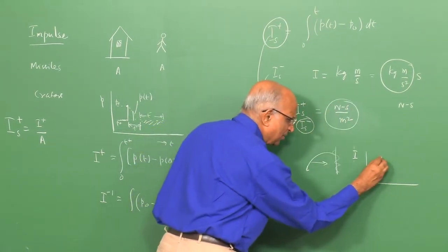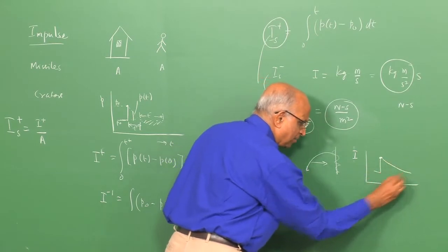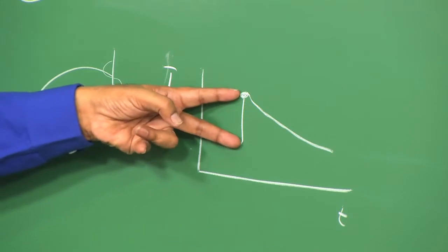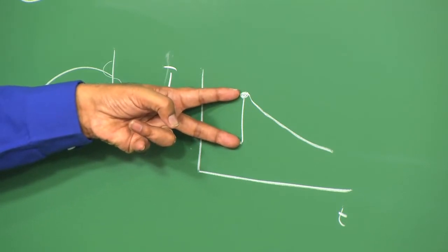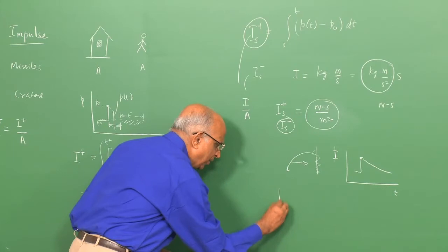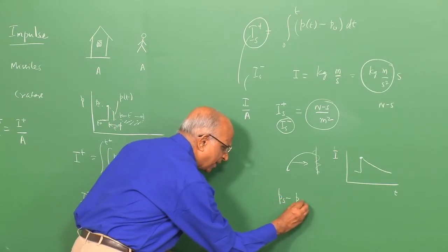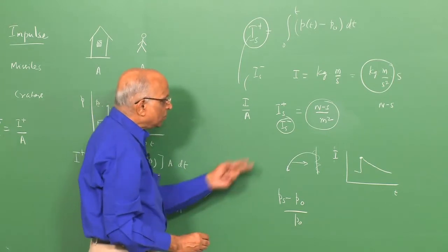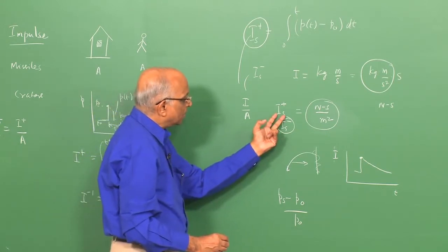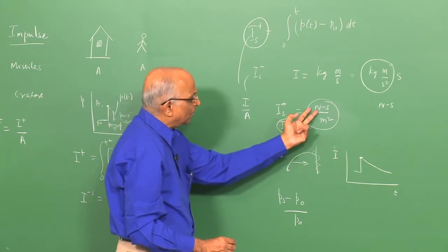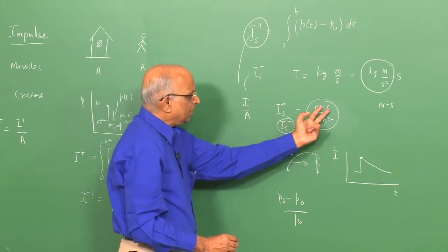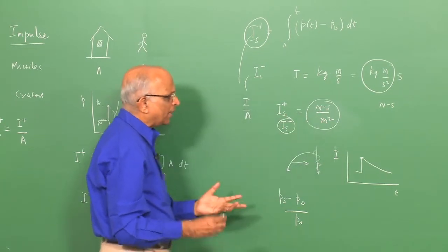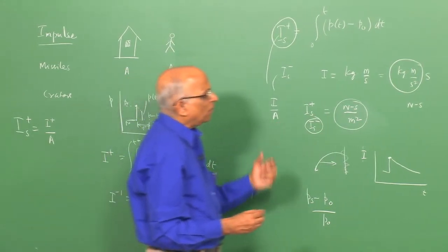We told ourselves initially there is a rise in pressure, and it comes down with respect to time. And what did we say? That the rise in pressure, that is the pressure behind the blast wave, we wrote in a non-dimensional form as Ps minus the ambient pressure divided by the ambient pressure. Can I also write the value of the impulse, instead of carrying a unit like Newton second by meter square, in a non-dimensional form? Therefore, we again take a look.